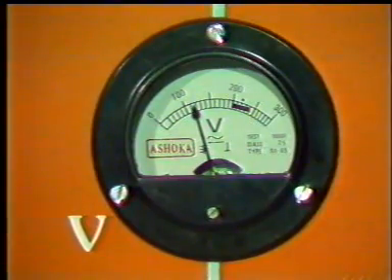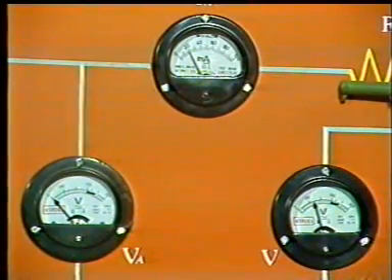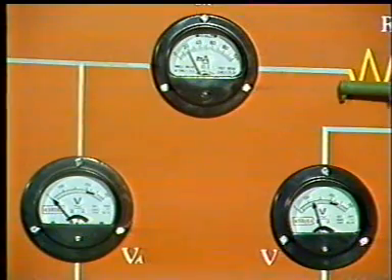Now the supply voltage is about 115 volts, but the SCR hasn't turned off still. This is because the anode current is not 0 and the voltage across SCR is still very small. The SCR would turn off when the anode current falls to 0 and the anode voltage equals the supply voltage.